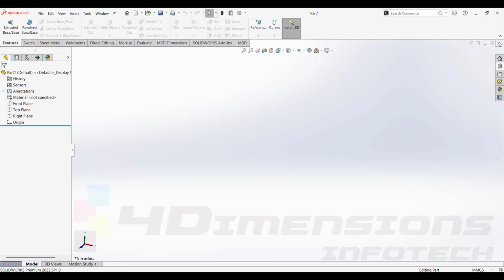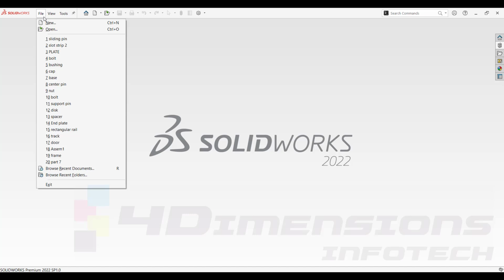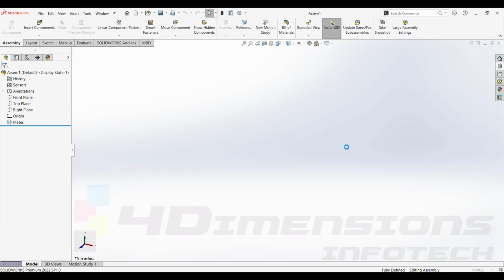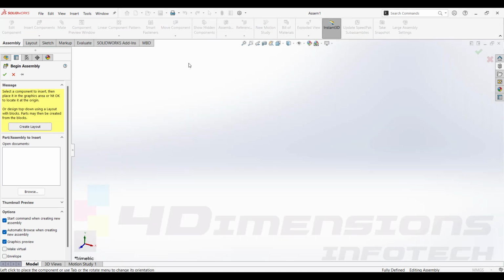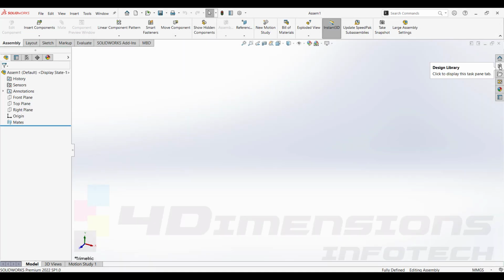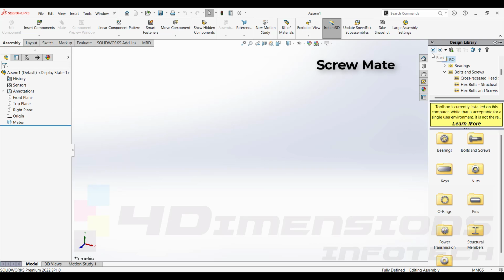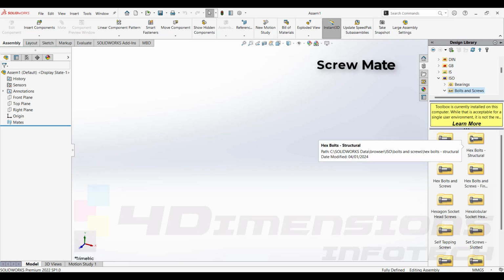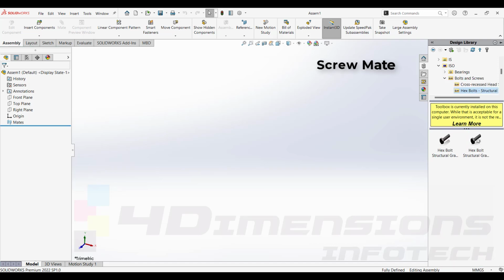So we'll change the interface here. I'll say file, new, and assembly. So in assembly, we can directly use library parts also here. So instead of browsing the parts, I'll go for the design library option. From this option, you can go back steps. You can see again the standards are showing here. I'll select ISO. In ISO, I'll select bolts and screws, and in bolts and screws, I'll select hex bolt structural.